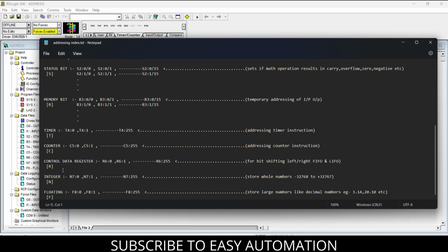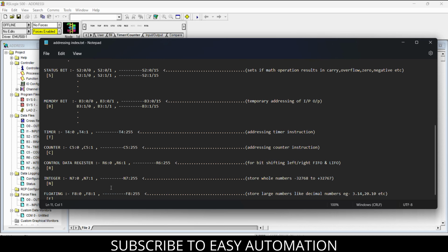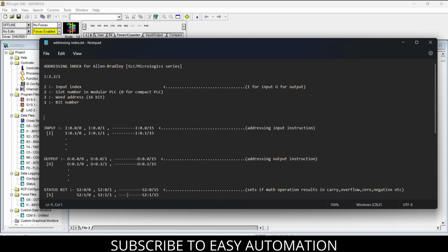Next are our control data registers, which are used for bit shifting, first in first out, last in first out, and operations like this. Next is our integer data register, which is used to store whole numbers from negative 32768 to positive 32767. The last register is the floating point data register, which is used for storing decimal numbers, for example 3.14 and 20.10. So this is about the addressing index for the RSLogix 500.